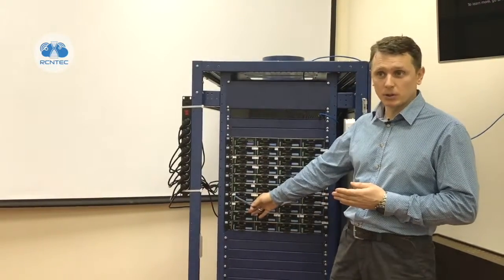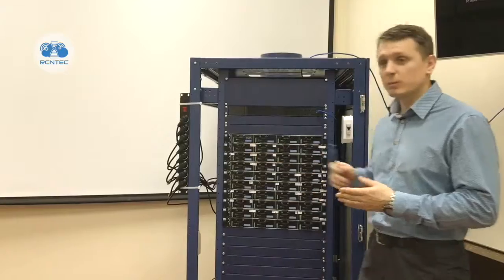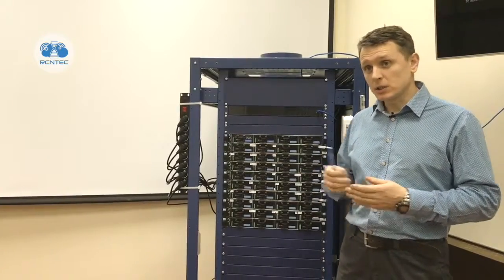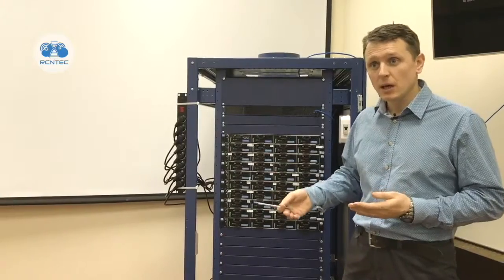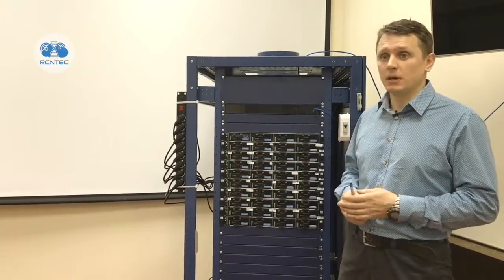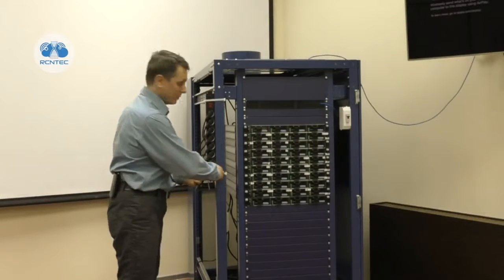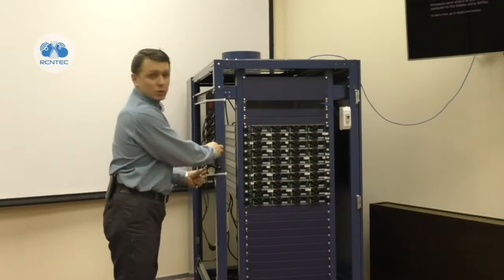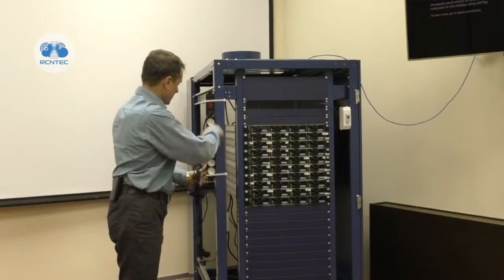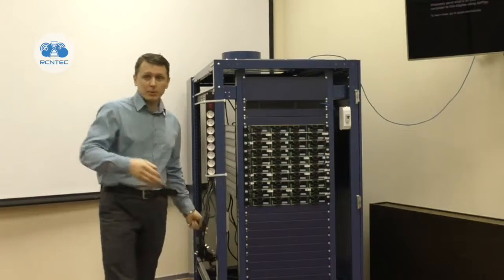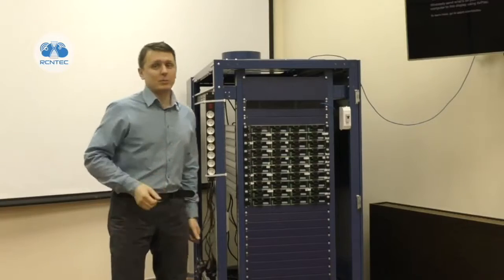All equipment is off and external picture doesn't reveal the source of failure. We need to locate the faulty device and recover power supply as soon as possible. The simplest way to do it is to disconnect all consumers. And that's what I'm doing now. Now I'll go and reset the circuit breaker.